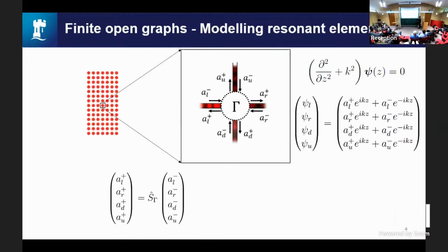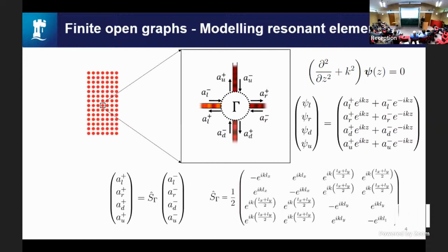All right, so back to where we were. There is a scattering matrix. You can define it in closed form with some structure. It's up to you. I said, okay, think of this one here, which has an Lx and Ly parameter. I substitute that in, and this is the scattering matrix I get, where I have an Lx dependence and an Ly dependence, and all of the trajectories on the inside are taken into account by that matrix. So that's how I describe an atom. There's a graph, it has trajectories in it, I solve it in closed form, and now I want to plug those atoms into my mesh, which again I've chosen to be square periodic. You may choose it to be triangularly periodic, anything you like.